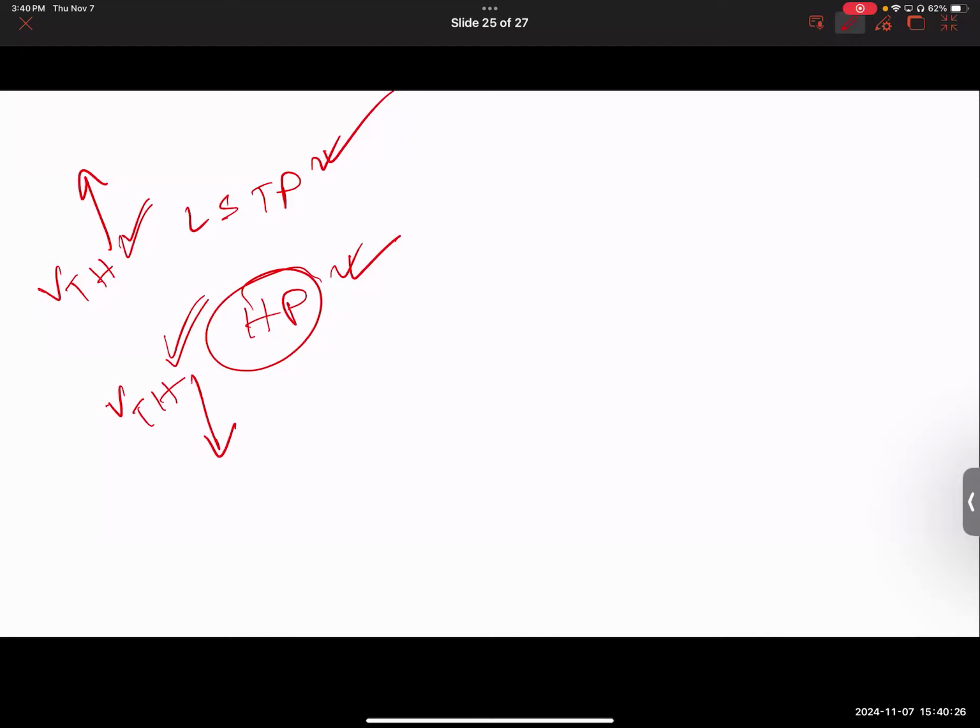When you send out the design to the foundry, they have to figure out a way to give you exactly that threshold voltage, right? 0.273 volt, 0.38 volt. Basically, that's how much resolution they can provide. They could get to millivolt resolution. The foundry is in that stage. At least when I interned, I realized, oh wow, you guys could do that. Control 1 millivolt. They have that much control. You tell me how many millivolts or volts of threshold voltage you need, we'll give it to you.